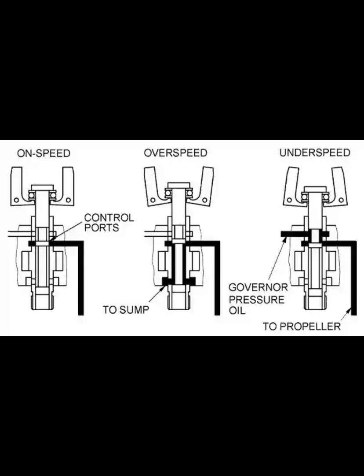The fluid is centrifugally forced through small tubes to the propeller's leading edge. De-icer fluid is ejected from a nozzle on the engine to a metal grooved ring aft of the prop that is spinning as fast as the prop. The fluid slings through holes drilled in the ring, then through discharge pipes, out across the leading edge of the propeller.